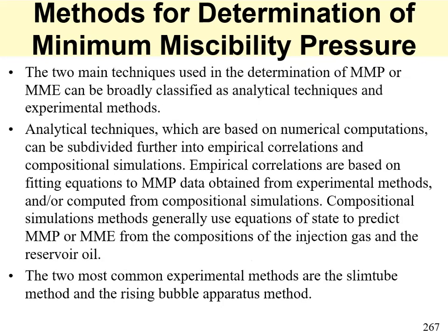This isn't covered in this presentation. That's determination of minimum miscibility pressure, but it's still good to highlight that you have analytical techniques and experimental methods available for determining the minimum miscibility pressure. As regards analytical techniques, they are based on numerical computations, which could be further divided into empirical correlations or compositional simulations.